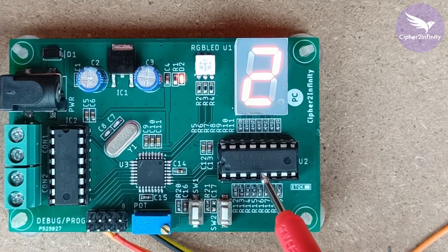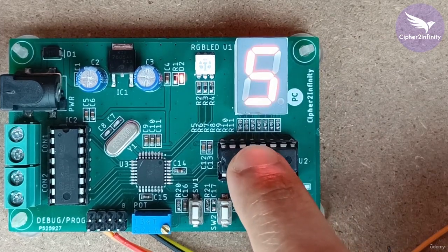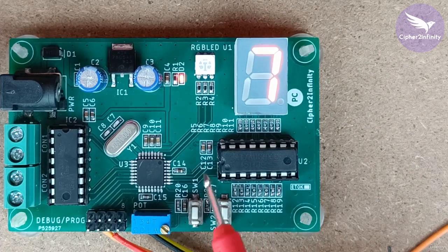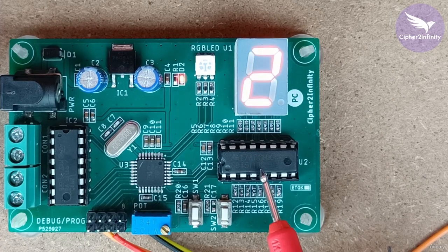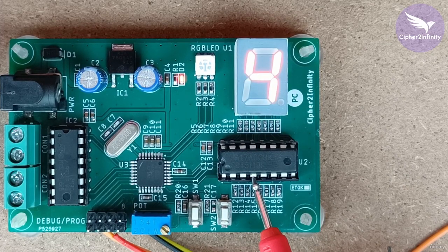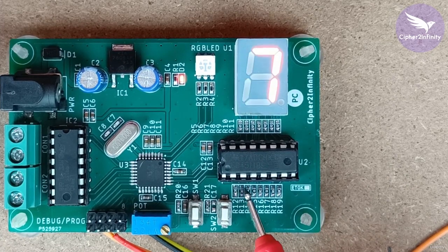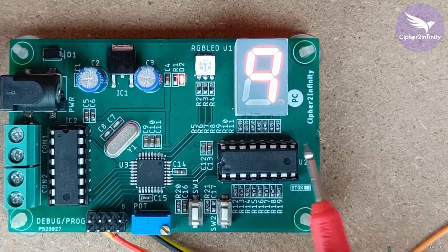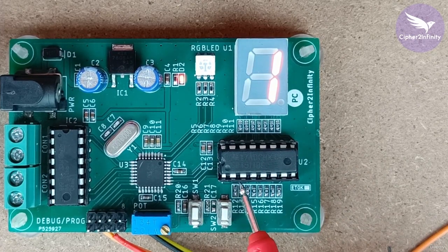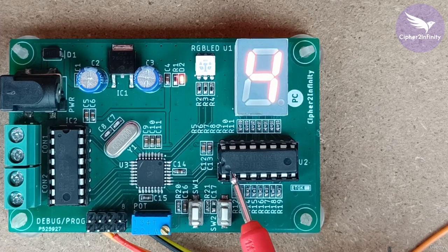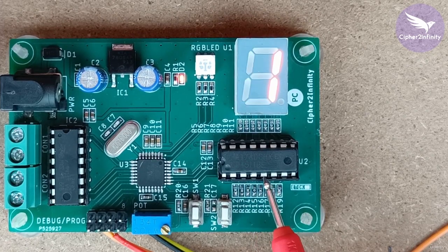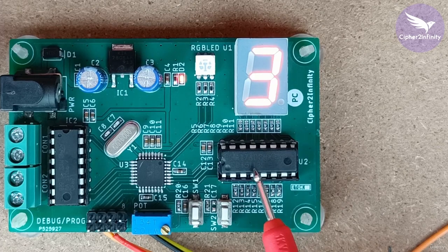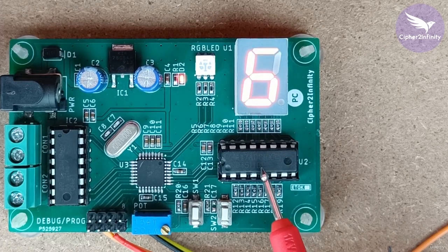And if the signals are not reaching, then what you can do is press this IC. Sometimes, because of loose contact, it might happen that the terminals of this IC are not connected to the pads on the PCB. So you have to make sure that the IC is properly inserted in this IC base, and once you press the IC, that will make the contact, and you will get the signals on the input pins, which are the ABCD pins of the 7-segment display driver IC, okay?